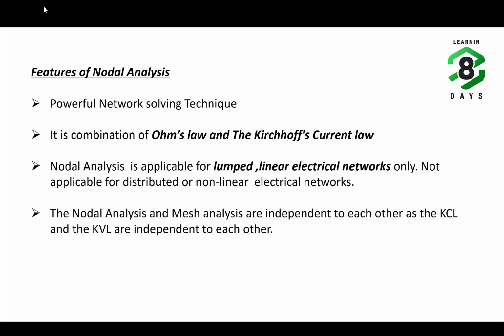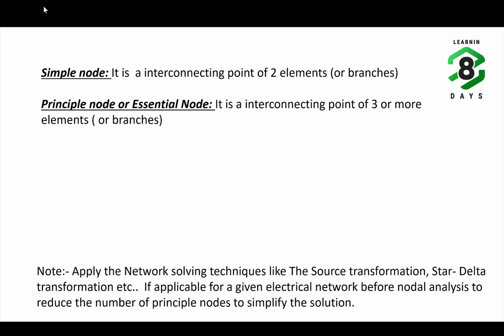Nodal analysis is applicable for lumped linear electrical networks only. It is not applicable for distributed nonlinear electrical networks. Nodal analysis and mesh analysis are independent of each other, as the KCL and the KVL are independent of each other. So these are a few features of nodal analysis.